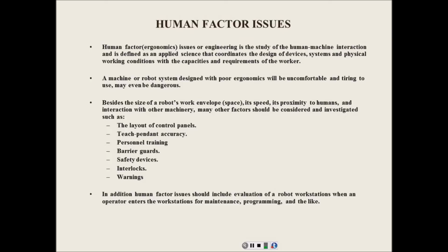So the Fanuc has what they call T1 and T2. And if you look at T1, it says 250 millimeters per second. If you look at the T2, it says 100%. Now the 100% is not when you're jogging the robot. The 100% is when you're executing the program with the teaching pendant. So that means to run it, you've got to have the deadman switch pressed.